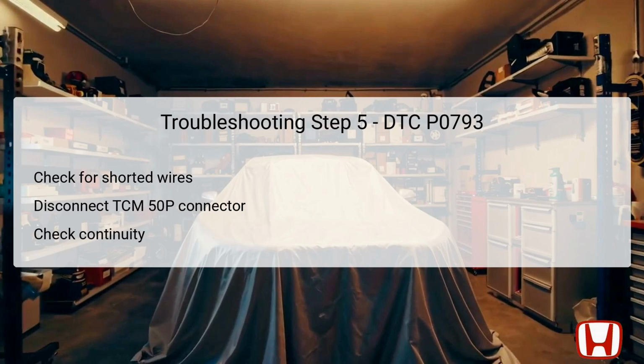A yes response indicates a short to ground in the NDR PWM wire, necessitating immediate repair of any issues found. If continuity is not detected, you can move ahead because it indicates that the NDR PWM line is intact without faults, leading you to the next troubleshooting step.